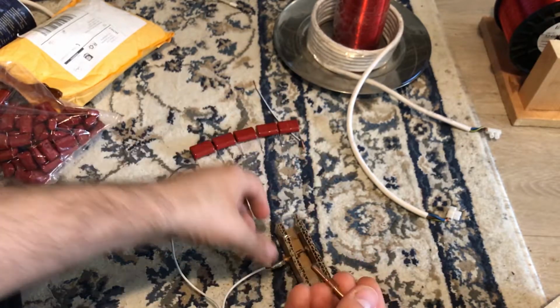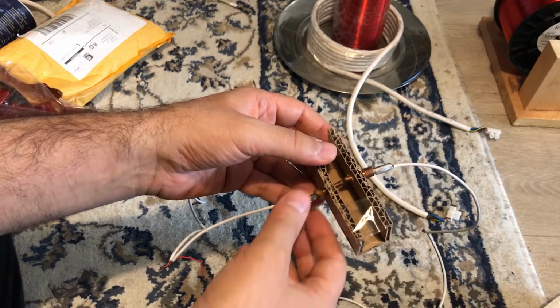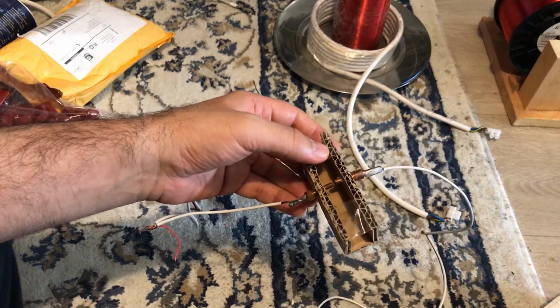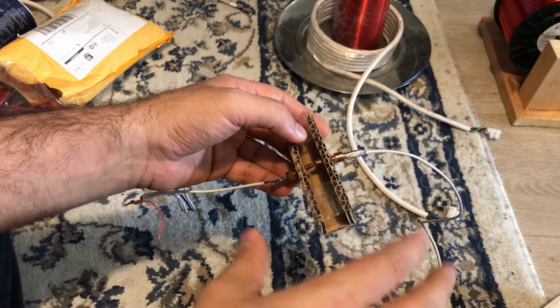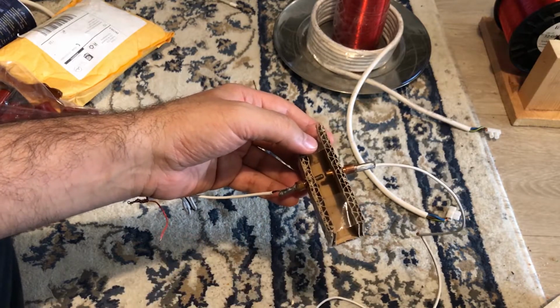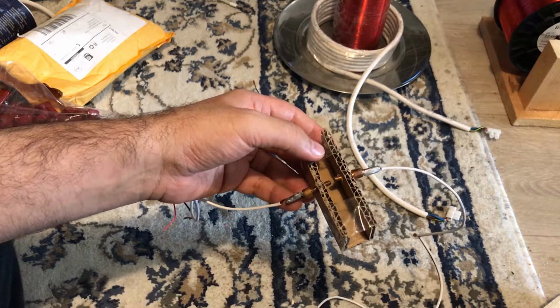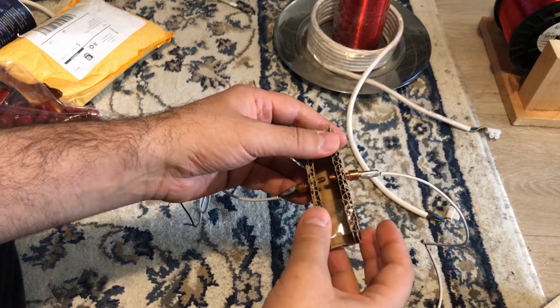Designing and constructing the spark gap is really important and it actually needs to be cooled down properly. In this case it is not cooled down. So if we apply large power through this Tesla coil, then this will get hot and the spark will stay there. That is a modification which we can do in other videos. But for this moment, this is okay.